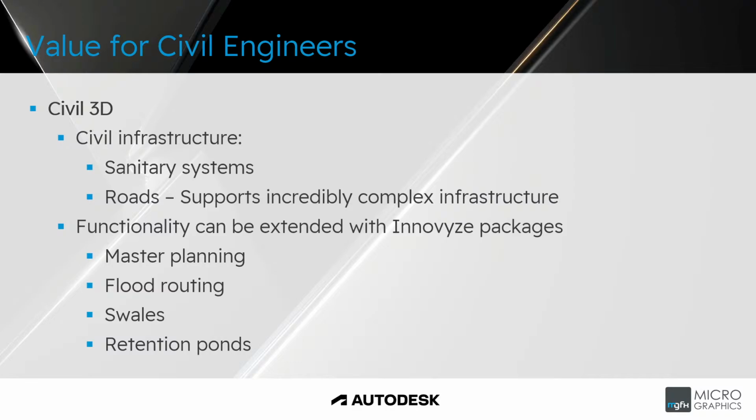I'm thinking especially of things like Procon's ProNet as an extension that adds that analysis and design functionality for water reticulation systems that we might want. So please chat to us about that. Like I said, when you have Civil 3D, that's fantastic. There's a lot you can do with it, but on the design side, you need to take cognizance of the limitations with it, and that you might need an additional package to add that design functionality. The Innovyze packages are phenomenally powerful, but they are expensive. So just keep that in mind.